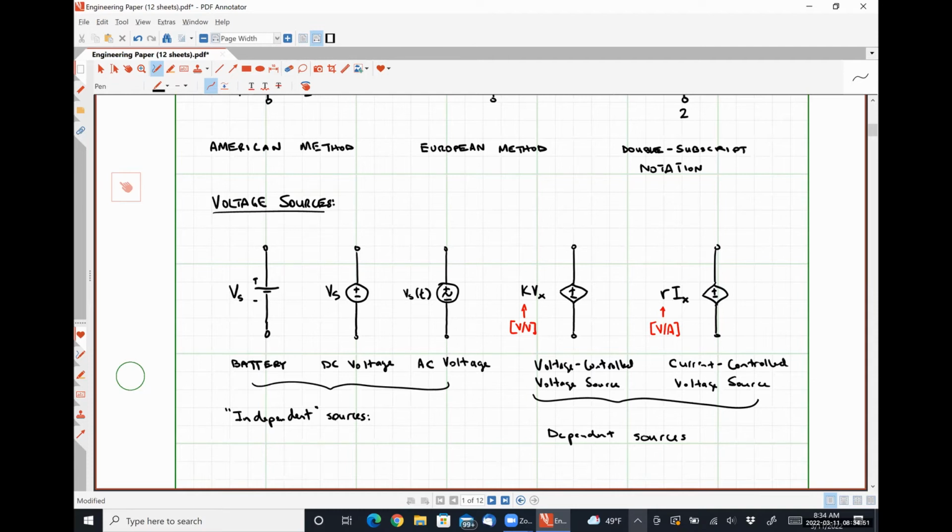All right, nobody's saying. Yes, ma'am. So for current controlled voltage sources, they only depend on a current somewhere else in the circuit, not voltage? Correct. The current controlled voltage source depends on a current. A voltage controlled voltage source depends on a voltage. They both have the exact same symbol, a diamond with a plus and minus sign indicating the positive and negative polarity terminals. So you can tell which one it is by what the controlling variable is. So if the voltage depends on another voltage, it's a voltage controlled voltage source. If the voltage depends on a current, it's a current controlled voltage source.